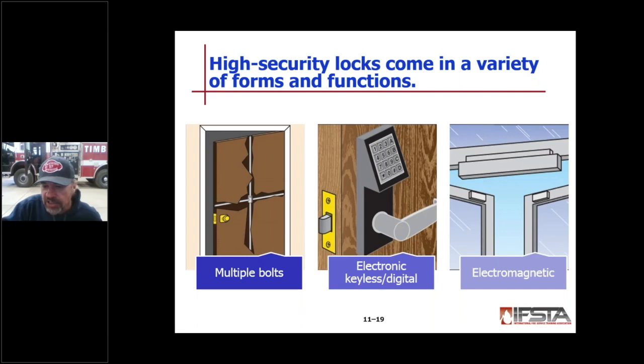When the electricity is shut off, these are typically programmed so that any electromagnetic lock will open. So it's a fail-safe open. But if we have to defeat these without the power being turned off, we'll have to take some additional measures, and it probably won't mean actually getting through that electromagnetic feature. We'll end up having to do something else.